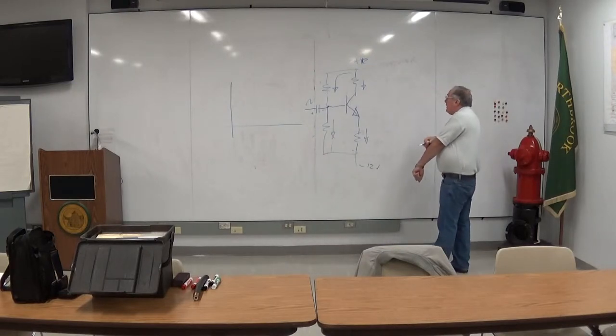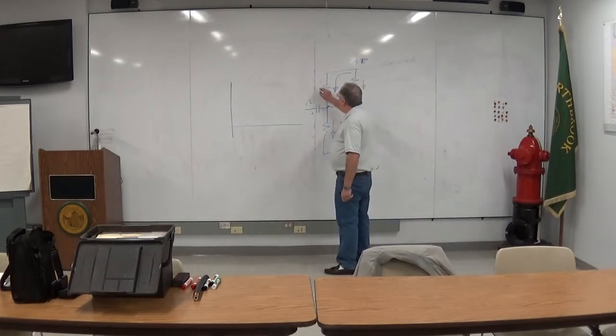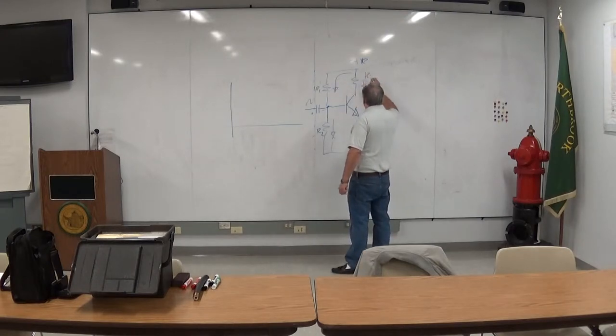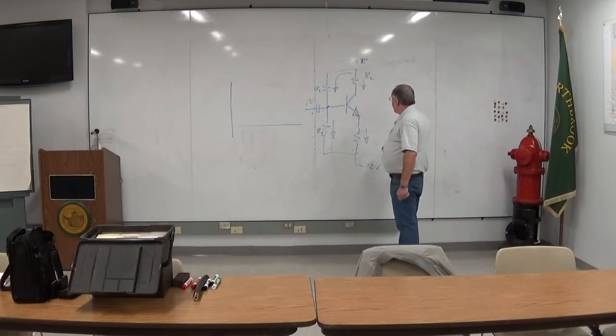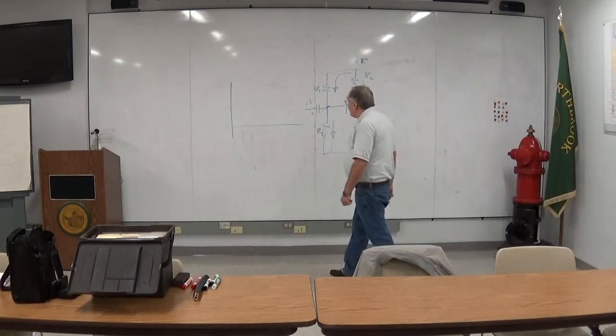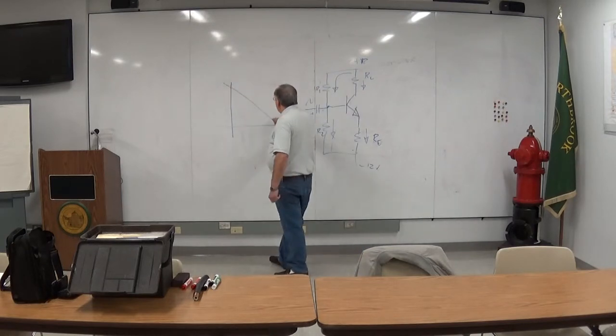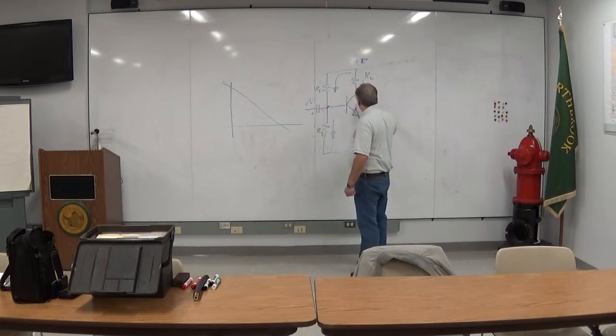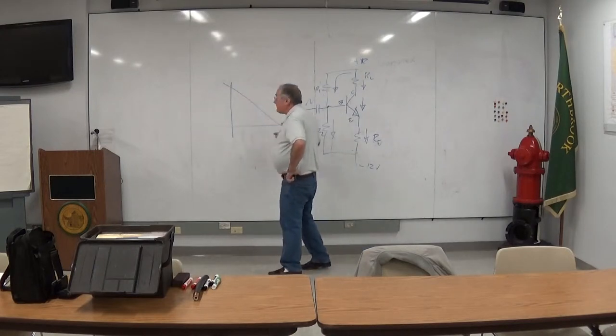And those values of those resistors, R1, R2, RL, because that's what I will describe as the load resistor, and RE, which is the emitter resistor, are designed so that when you have a transistor, whatever value of current flowing through this collector to emitter path, remember this is the base, will fall on this straight line.